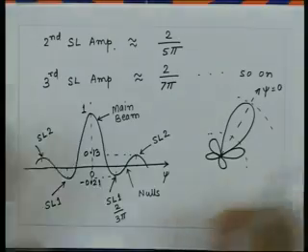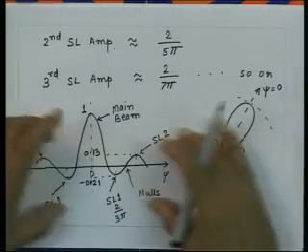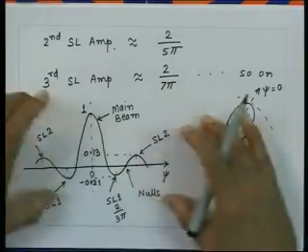If I sum up all together, you will see there is a substantial loss of power in the side lobe directions compared to the main beam direction. So, the side lobe as such is a very undesirable characteristic of the radiation pattern, because that essentially represents the loss of power in the radiation pattern.